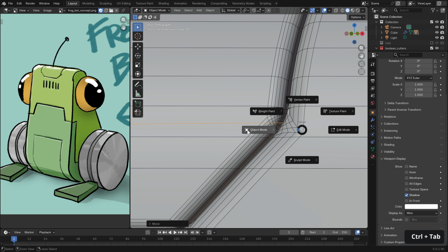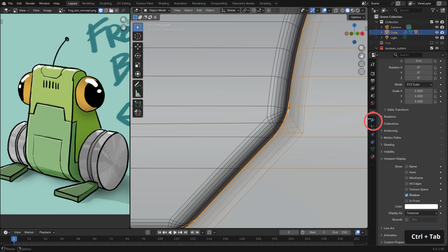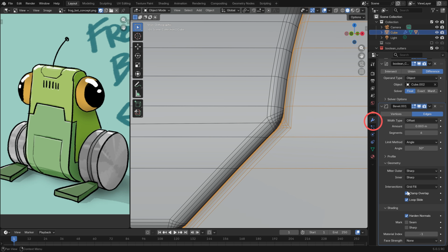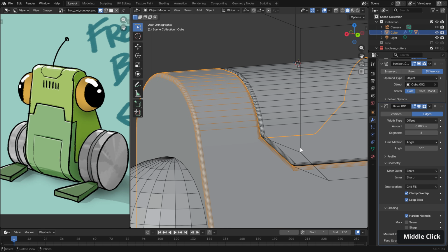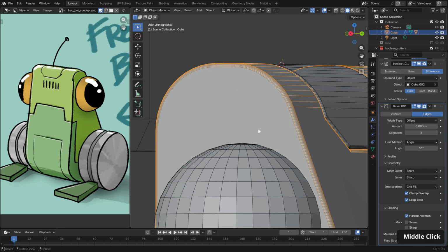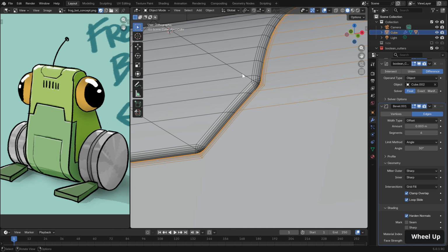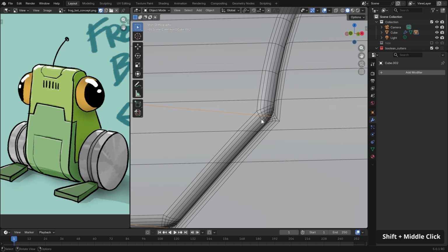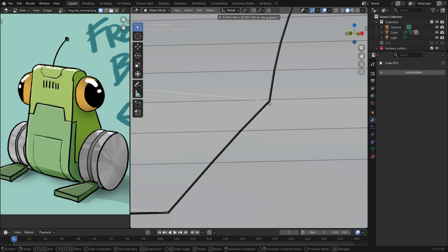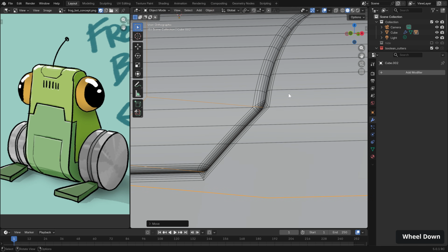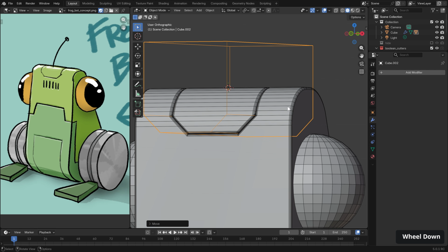So let's jump back out into object mode. I'm just going to re-enable the clamp overlap, and we're still getting some reduction in our bevel. Just check the rear side. Nope, those edges are completely clear of any of our target edges. So another thing we can do, instead of making the edge as far away from the two other edges as possible, we can basically get it so close that there's a calculation rounding error that treats the cutter and target vertices as one. And there it is, very nice. And now we have our nice wide bevel back.